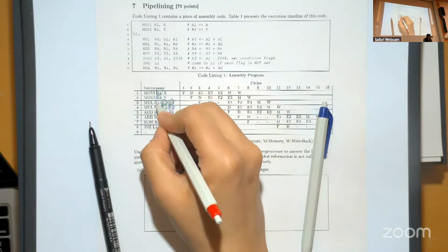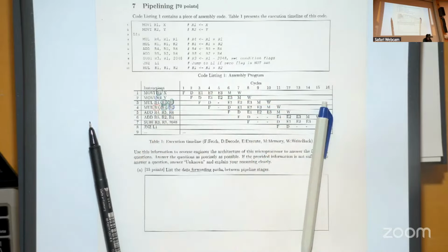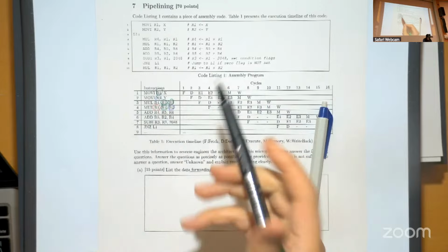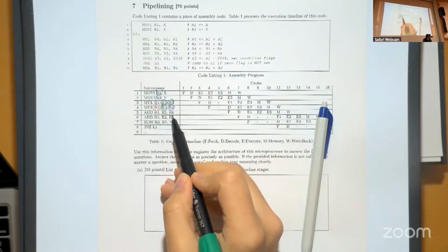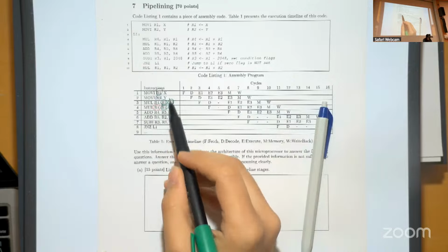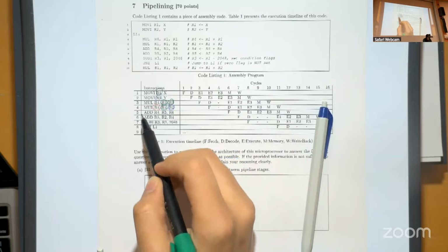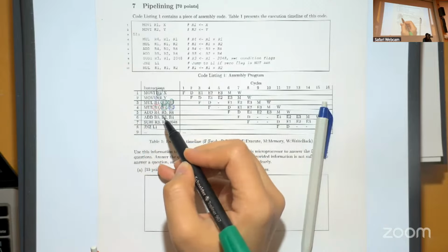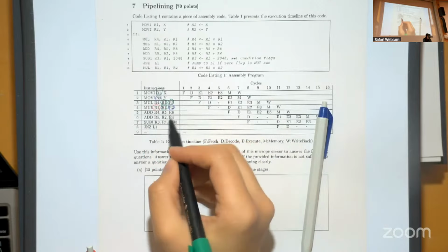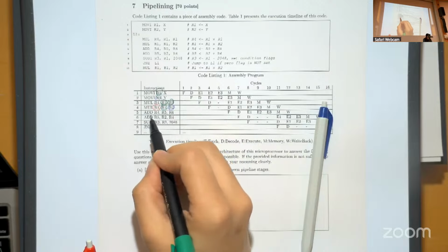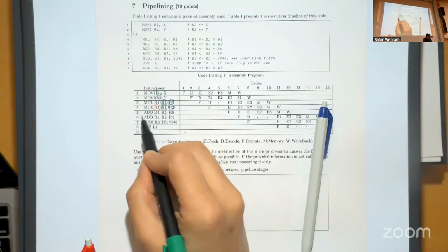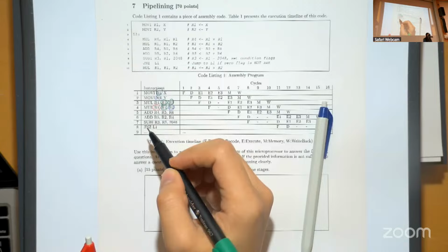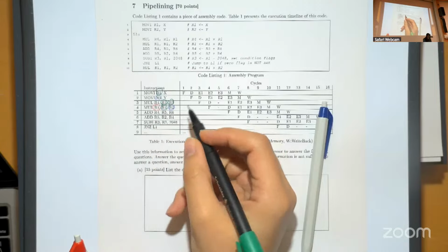So I will just mark it with another color. And next we have an instruction with R4, R5, and R6. These are not related to the earlier ones. You can also think that, okay, R4 was written here. Does that create a data dependency? The answer is no, because you basically overwrite the result in the instruction 5. So it's not read, it's written again.